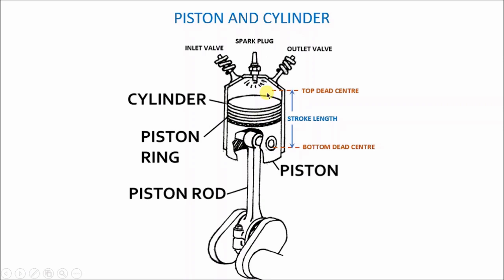But now, because the mixture that is inside the cylinder has nowhere to go as the piston is moving up, because both valves are closed, that mixture will begin to be compressed. And as compression is taking place, the temperature of the mixture is going to increase, and the pressure is also going to increase. And eventually the piston will reach a position that is very close to its topmost position, which is called the top dead center, TDC, okay?